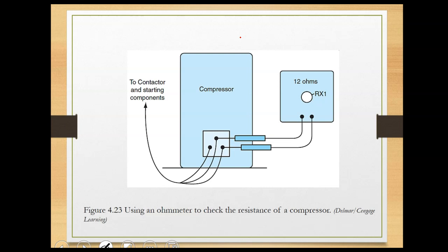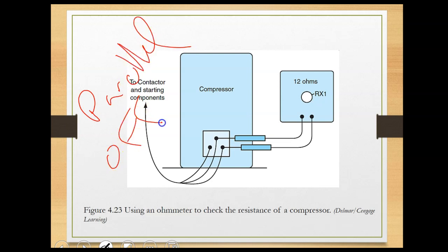This is to measure the resistance. One thing about resistance, it has to be in parallel. Also, the power must be off. Do not measure resistance of things when they're on. That's very important, otherwise you might zap yourself. And again, the resistance of a lot of loads changes as it heats up. Whenever something is on and it gets hotter, the resistance will increase.